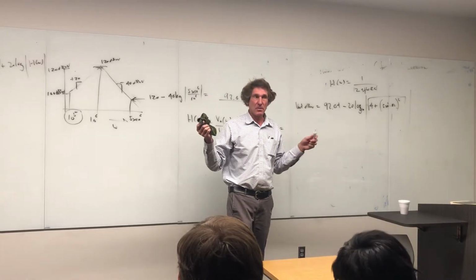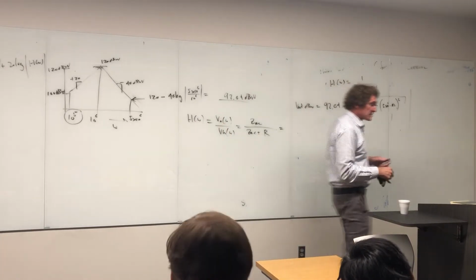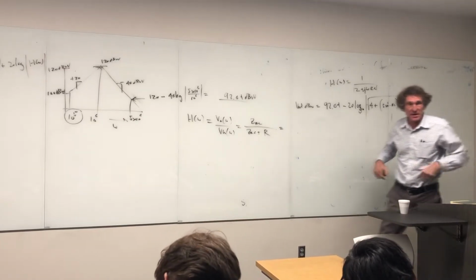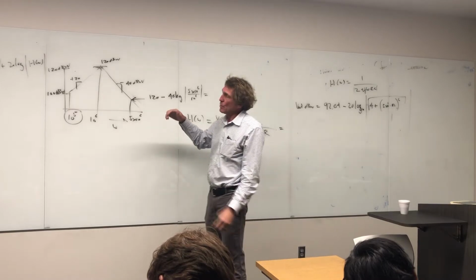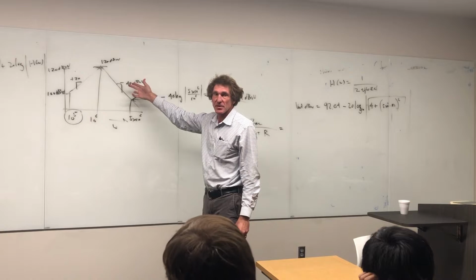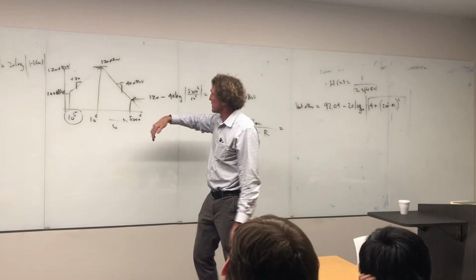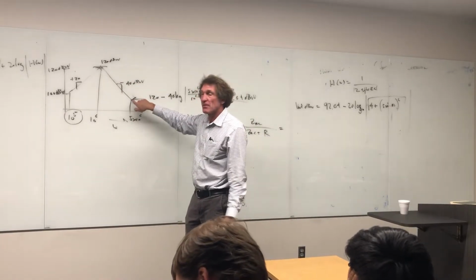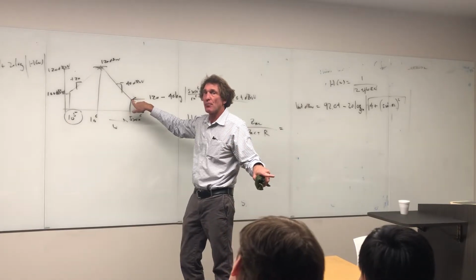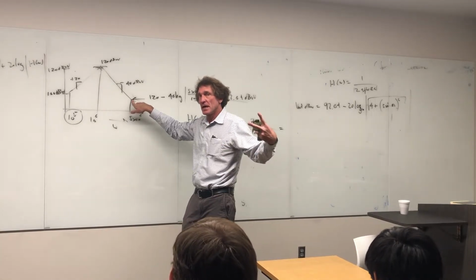The problems I gave you weren't hard, but you had to be attentive to what we're doing. And by the way, this is really EMC stuff. Here's a little insight: with the FCC, they give you this information about the input signal. You have a spectrum analyzer or a network analyzer, and you can move the cursor and figure out the value right here. Then you have to see if after your filtering the output is low enough to meet FCC regs. There are certain allowable output levels and you have to be below them.